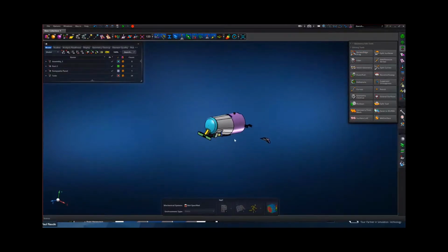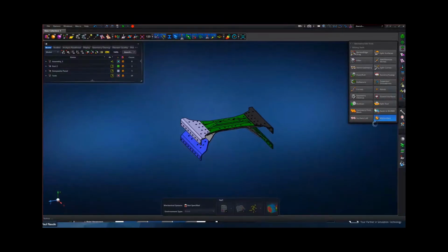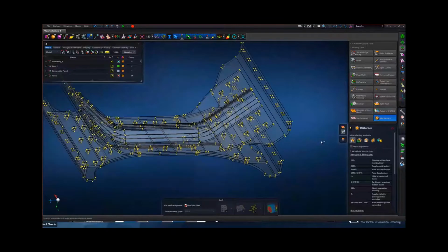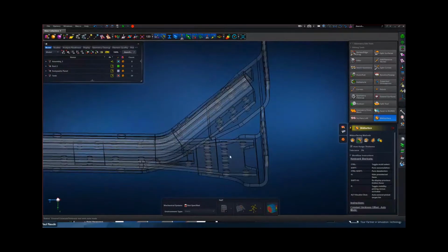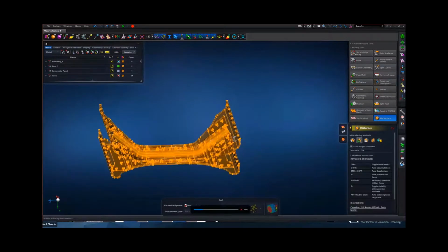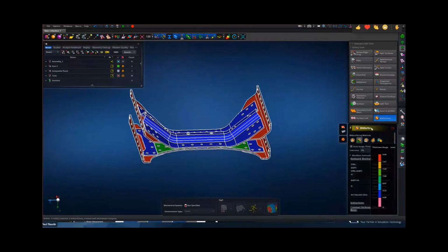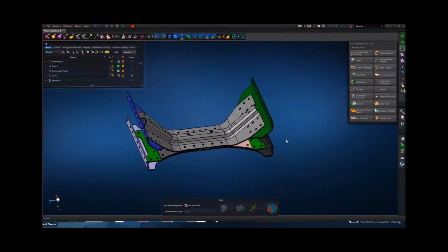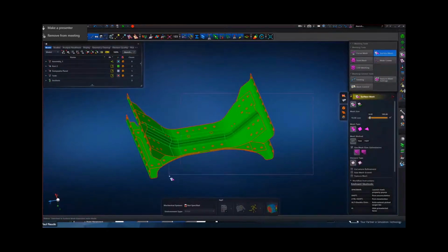All right, so to start, I'll quickly demonstrate the Midsurface tool on this particular assembly. So let's just show only this guy. Midsurface tool, the default is the manual method. I always skip to the second one. This works fantastic for constant thickness solids. So like in this case, we have a number of plates that represent parts of a constant thickness. You simply select all the parts and it's automatically executing your task, and it also assigns your thicknesses directly. So if we hide the solids, we now have midsurfaces that represent those parts. We can mesh them in one go.